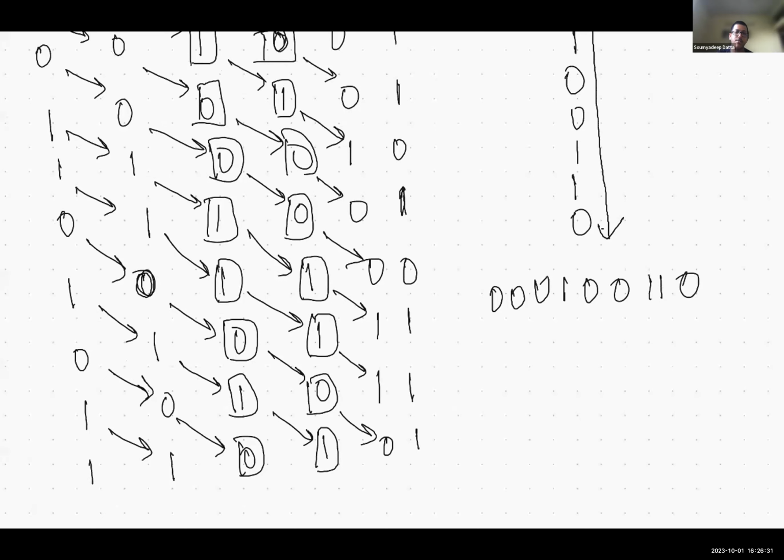All that is there is the working of a shift register: it will just shift the value from input to output after one time delay. That is all there is. Any questions? Sir, X4 is the output, right? X4 is the output, yes. X4 and output are actually the same, but the first initialization you won't take. You will take it after one time delay.